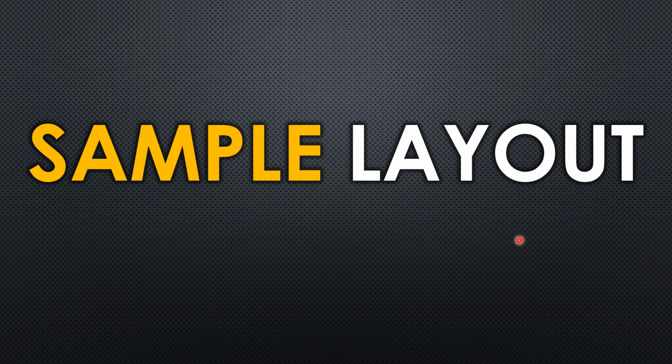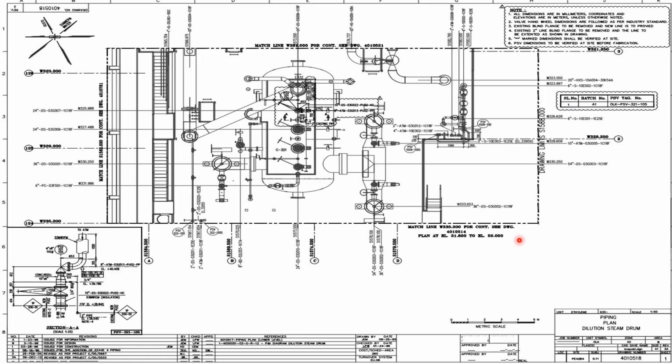Let's see some of the sample piping layouts which are actually used in industries. This is one type of layout where you can see how the equipment is represented in plan view, and at the same time there are some activities carried out. These activities are shown over here in clouds. So generally in any piping layout, if you are going to modify some area, those areas are shown with clouds. That is to identify for new readers that this is the area where modification has been done.